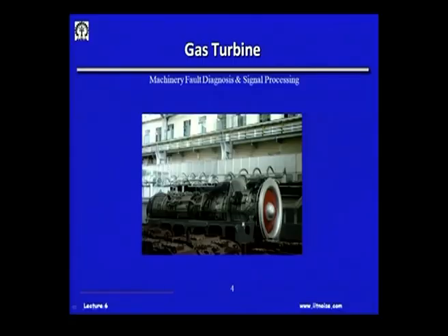Suppose another one has another amount of unbalance, it is going to give you a radial force. So, there could be a couple. In this couple, they are going to give rise to a lot of forces, though this turbine is put on a structure or a platform, and this platform is rigidly mounted to the hull of the ship or fixed to the wing of the aircraft.